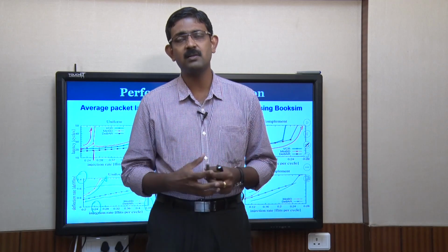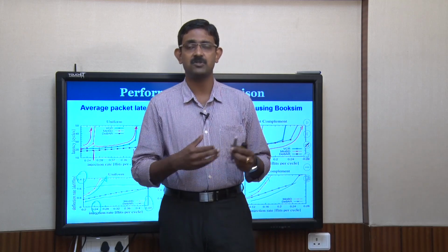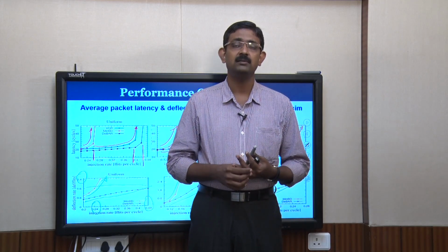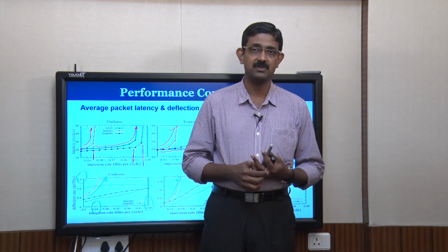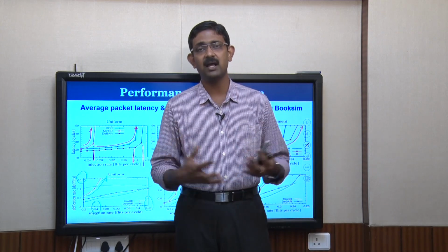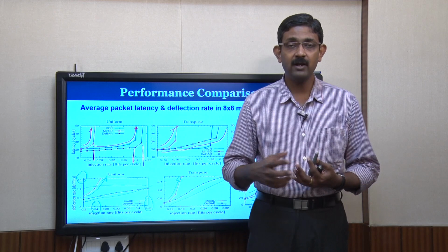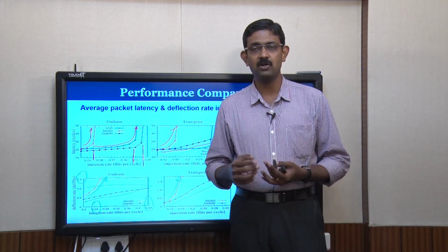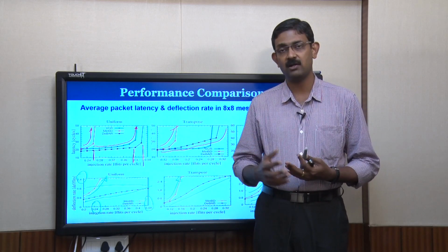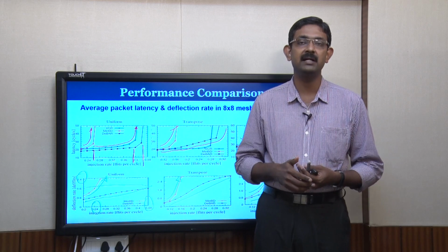So, the whole concept of moving towards bufferless deflection routing, which was mentioned in the CHIPPER paper, was to reduce the area as well as power consumption, because we are getting rid of buffers. But once we do not have buffers, at higher traffic rate it will lead to heavy deflections. And that was being mitigated by introducing the concept of side buffers, first proposed by Chris Fallin et al. in the MinBD paper, leading to the MinBD design.